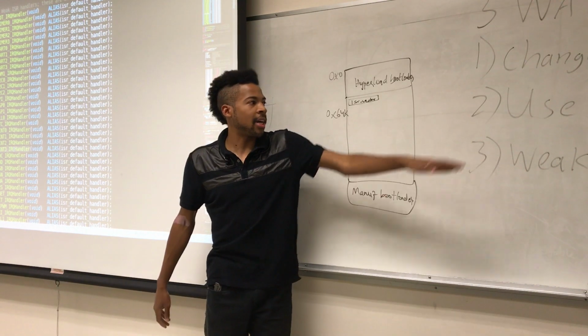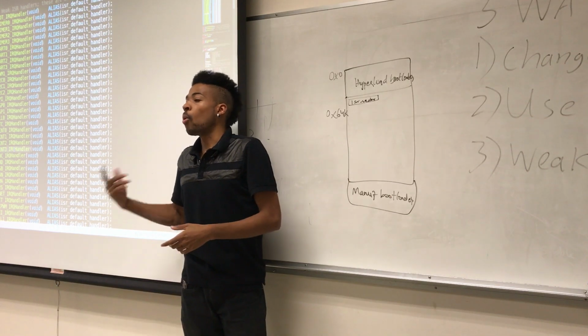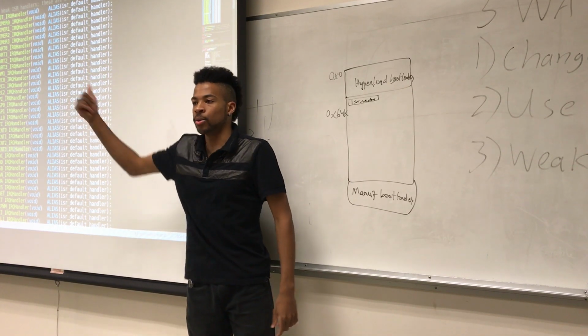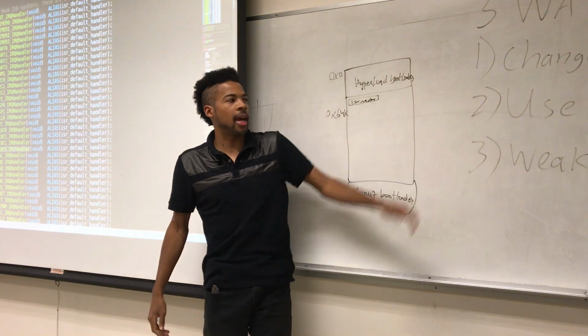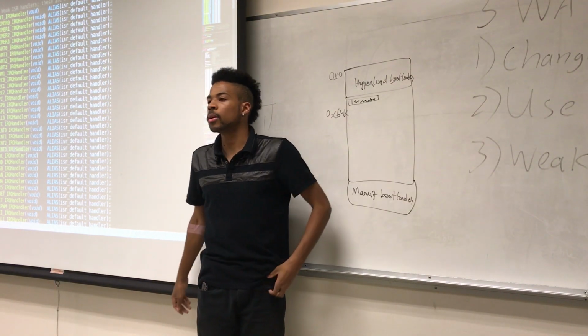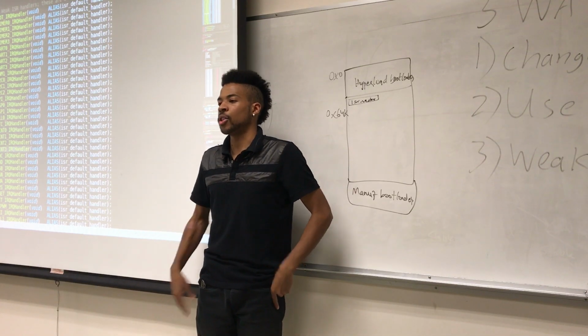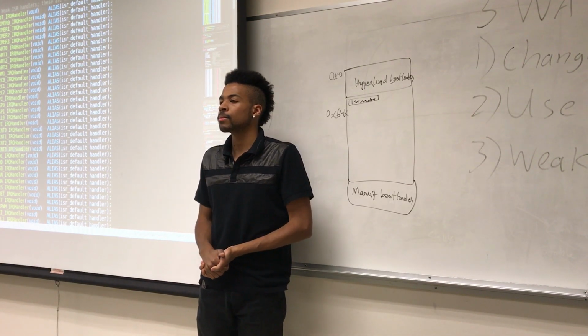one cool thing about having the ISR register function is that if you wanted to, on the fly, you could swap out the interrupt service routines. You have a little more flexibility with the ISR register function. So I usually suggest using that. Just give it any arbitrary function, and that will become a service routine at that point.